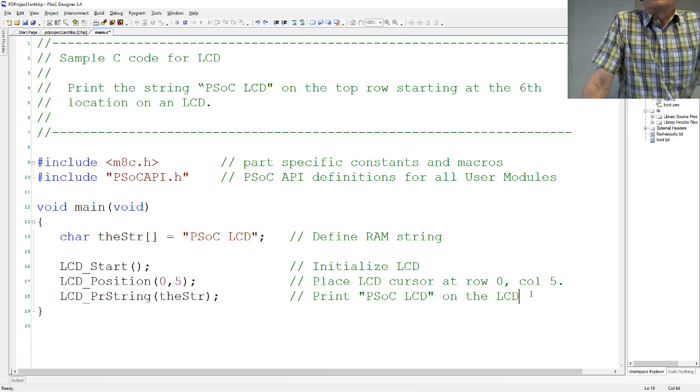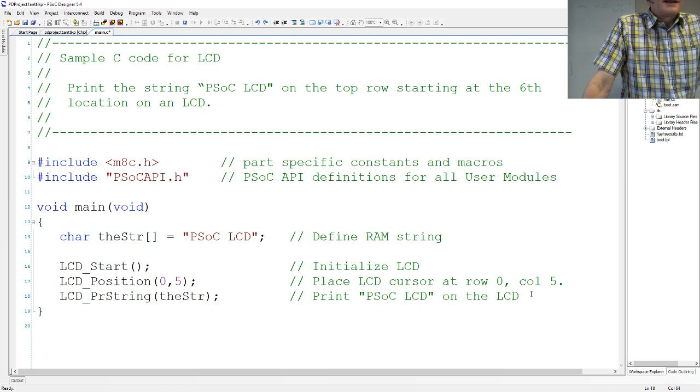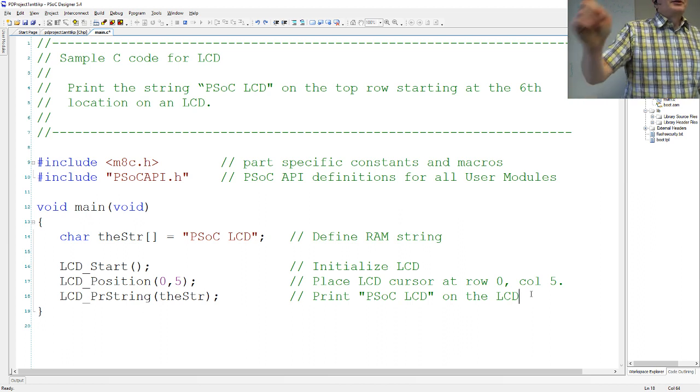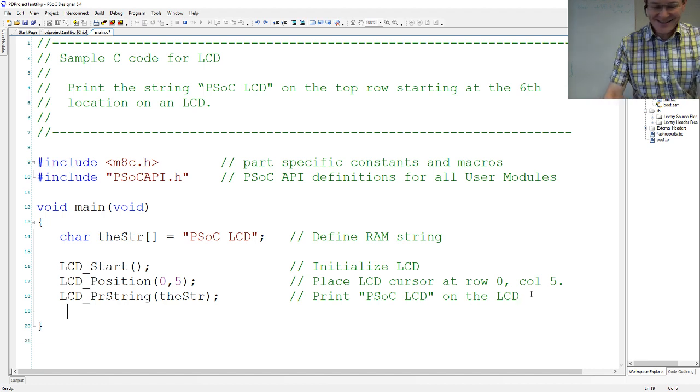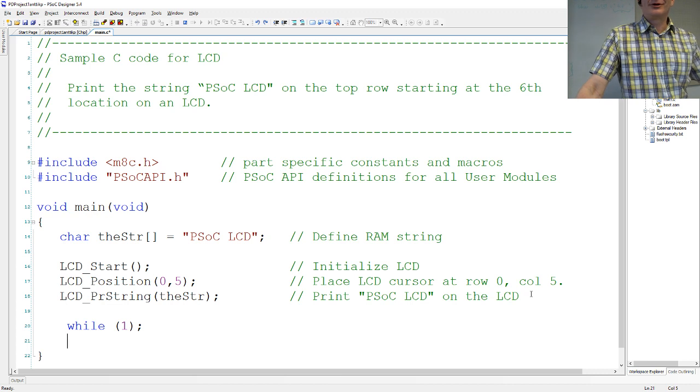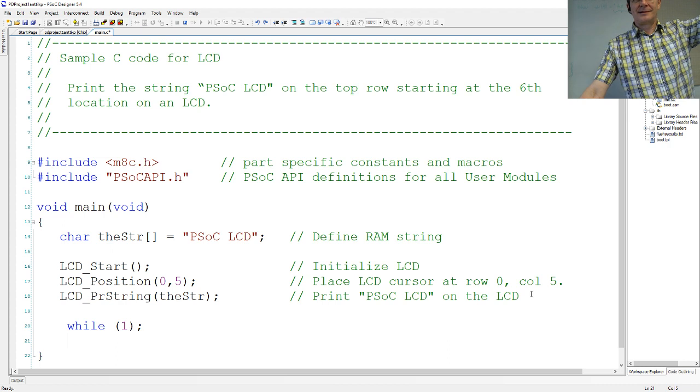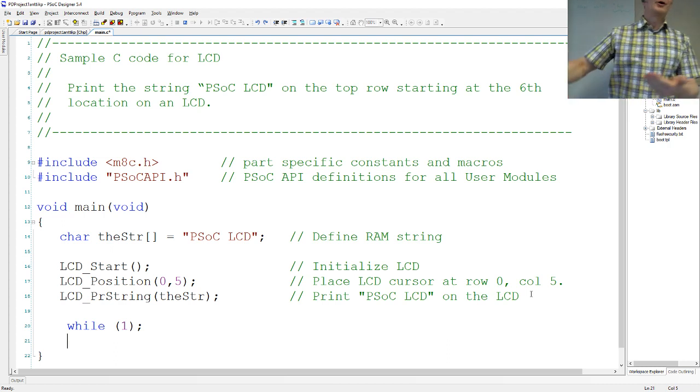What is missing? You have been doing some microprocessor coding before. What is missing from this one? Yes. I call it operating system. Yes, so this is microcode, so basically it should have the loop forever at some point, since you don't want to exit this main function without knowing where it exits, because it's such a function. After that last line, it goes somewhere.